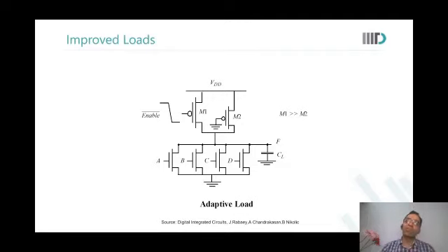See, why would you not have made M2 much larger? Had you made M2 much larger, static power would have increased significantly. Right, sir. Now you've actually saved leakage by this method without compromising on rise time. You've done both. Right, sir. Got it. Okay. Thank you.